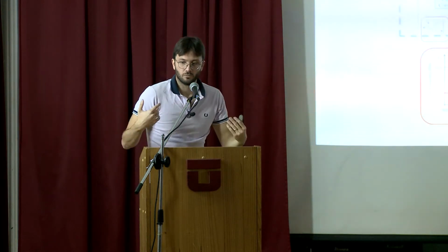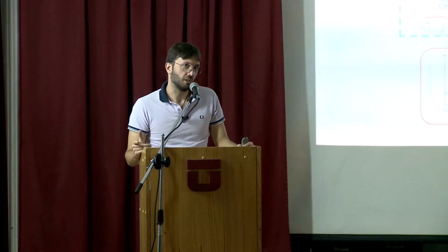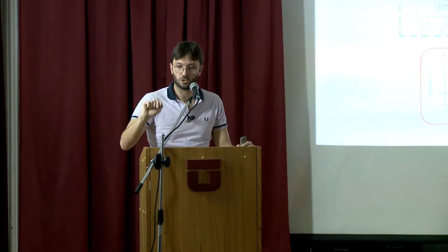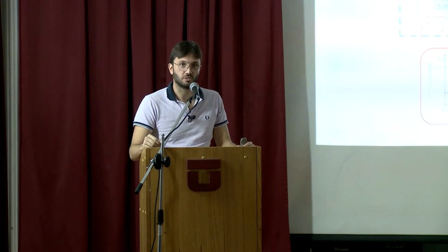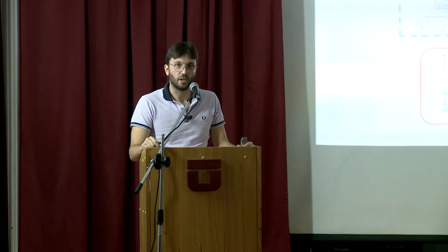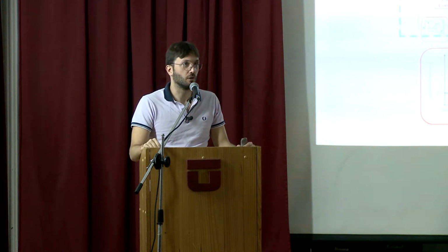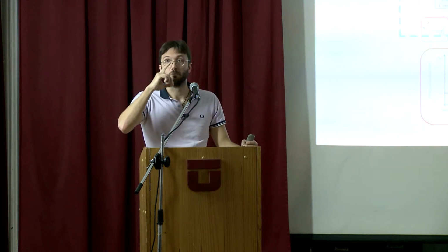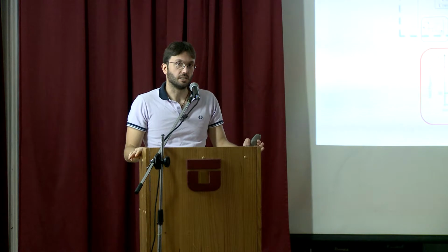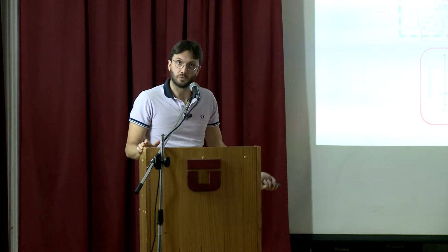By the way, I can also have a communication interface, and the control center actually tells me, look, conditions are fine. You can allow reverse power flow up to 0.2 per unit. It's another possibility. But otherwise, I just say, I prevent completely the reverse power flow.